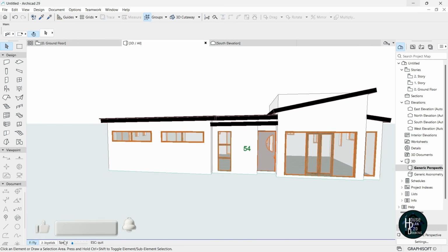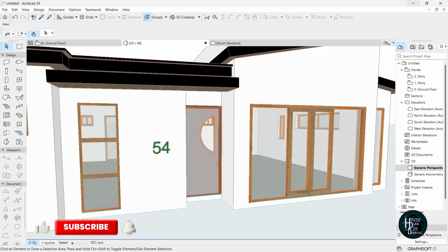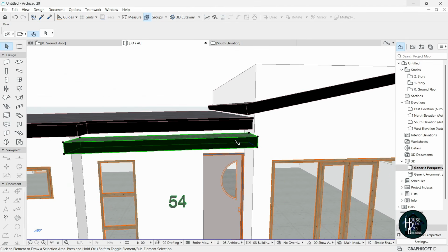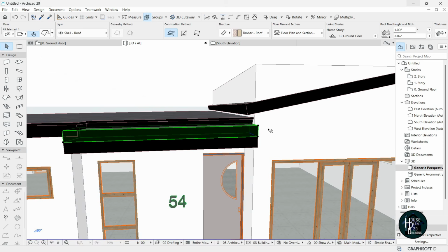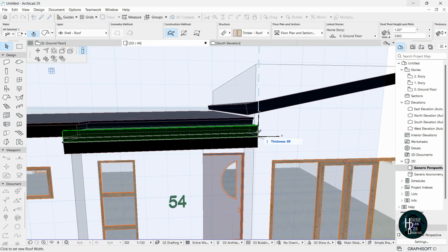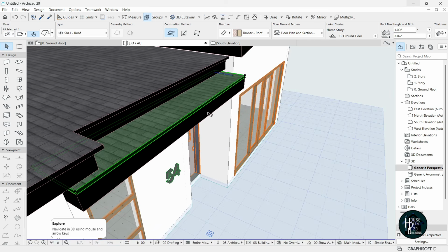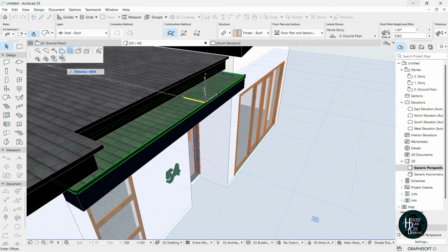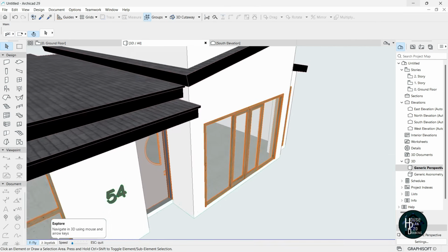Now I want you to come to this other side here, click this, press Ctrl Shift D on your keyboard, select this, select the top surface, reduce this by 50. Okay, click enter. Then you want to come to the side here, try and move properly, click this, and then make sure you're selecting the offset edge because you only want to offset only this side. Okay, then click 80, click enter. Okay, you want to do the same thing for this other side.